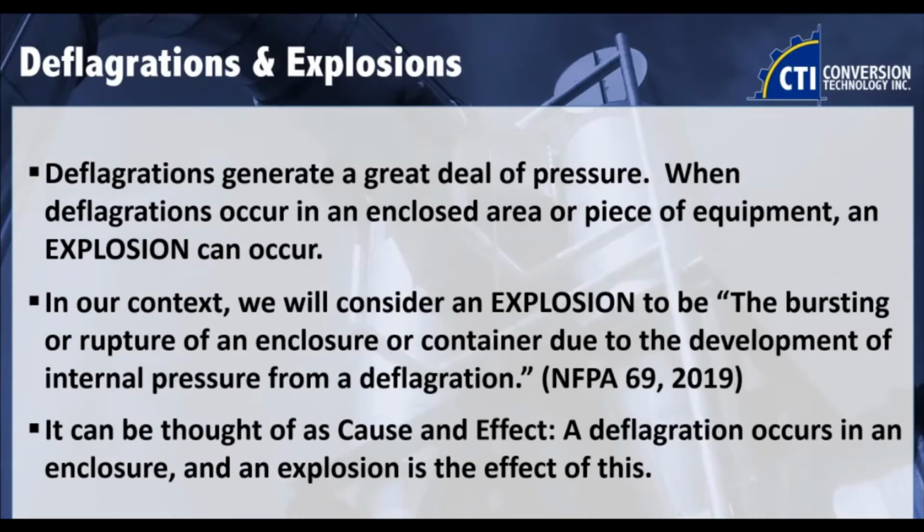So when a deflagration occurs in an enclosed area or piece of equipment, that's what the explosion becomes. We'll consider an explosion as the bursting or rupture of an enclosure or container due to development of internal pressure from a deflagration.